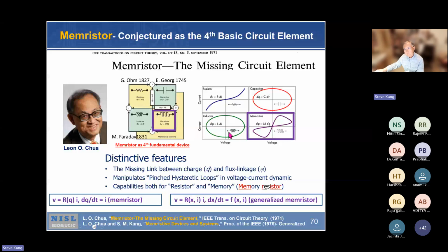What is different for the case of a memristor is that it passes through the origin, just like a resistor. So whenever input is 0, output is 0. So it must pass through the origin. But it has a memory effect, some hysteresis. That's a memristor. So, the voltage-current.